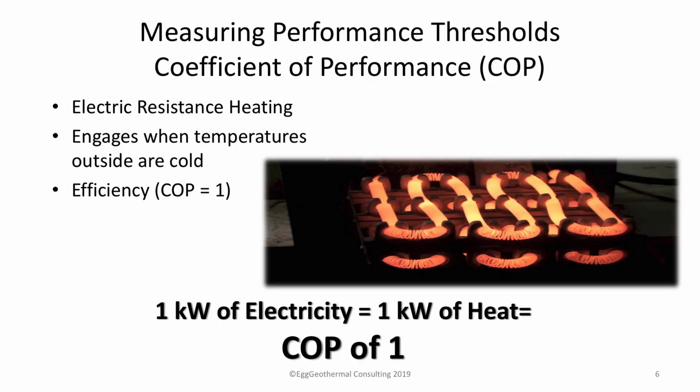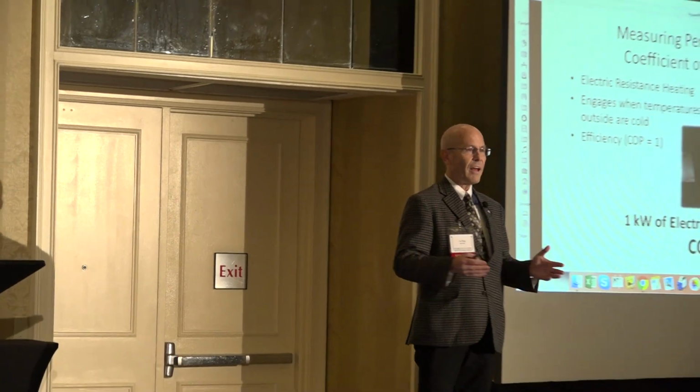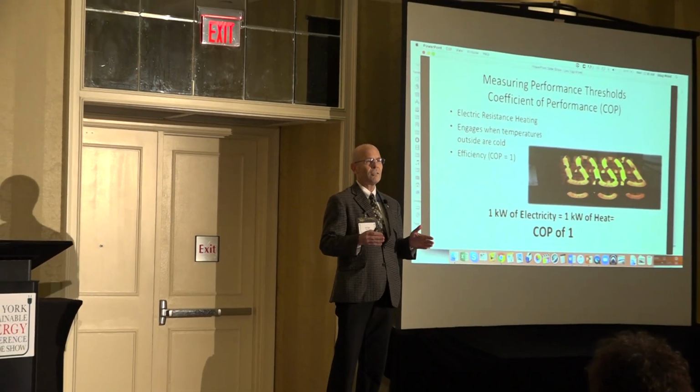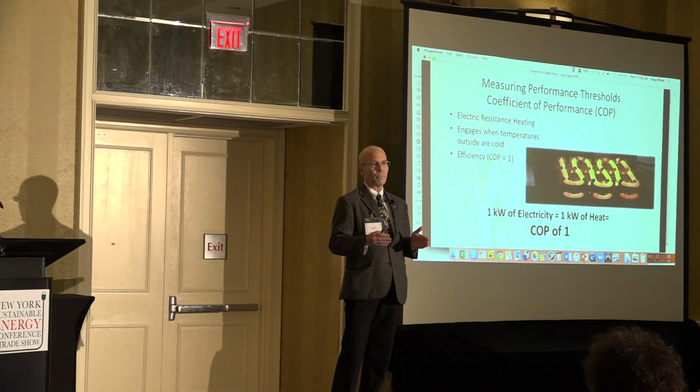In order to truly understand the magic of heating appliances and cooling appliances, you need to understand how they're rated. They're rated in something called coefficient of performance. For example, a gas furnace, if it's good, is going to be between 90% and 98% efficient. That's a 0.90 coefficient of performance. An electric resistance heat strip, for example, a room heater or a blow dryer, is 100% efficient. It has a COP of 1. So hopefully that makes sense. Let's move on from there.